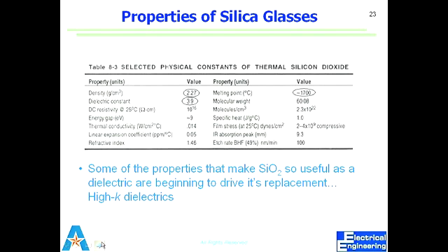But they will want to maintain that structure. So one will be under compressive stress, the other one under expansive, tensile stress. We don't see that with silicon dioxide, which is to our advantage. Conductivity is also in the same ballpark, which is good, so you can remove the heat and there are no hot spots at the interface.